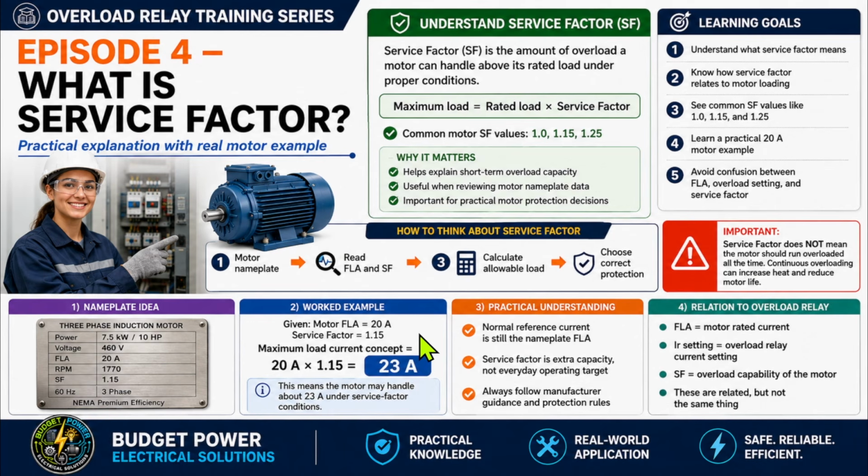The actual overload setting has to follow the applicable requirements, motor information, and overload relay manufacturer's instructions. The first practical habit is very simple. Read the motor nameplate before touching the overload dial.